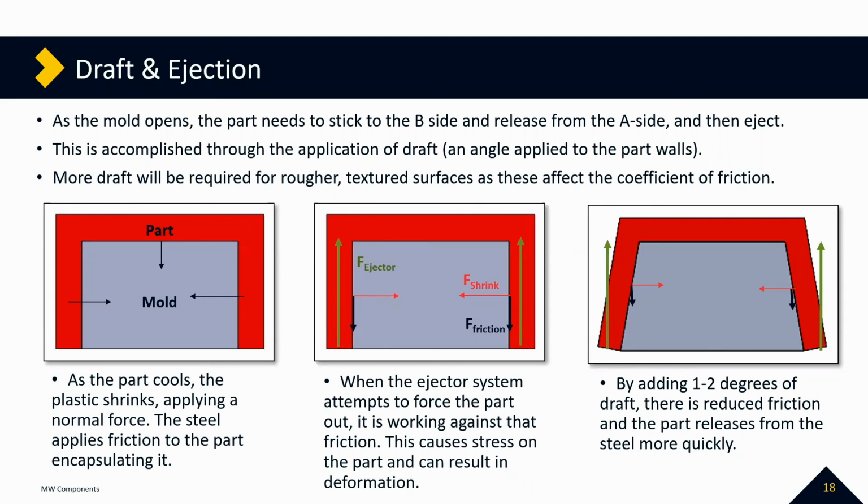The other thing is recyclability. How easy is it for my part to get processed in a recycling plant or something? And that really comes down to, can I make my part out of a single material? Does it have to be an assembly with metal screws in it, which are really difficult to get out and can really confound and stop the recycling process? There are ways around that: snap fits, press fits, things we design around very often. And that kind of thing, really. It doesn't have to be an assembly, or can this entire assembly just be made out of the same polymer or material?